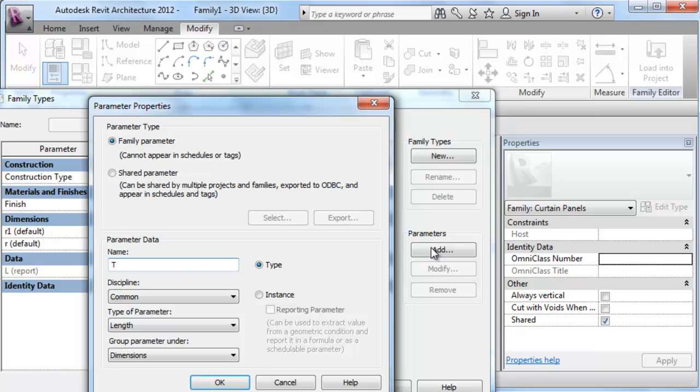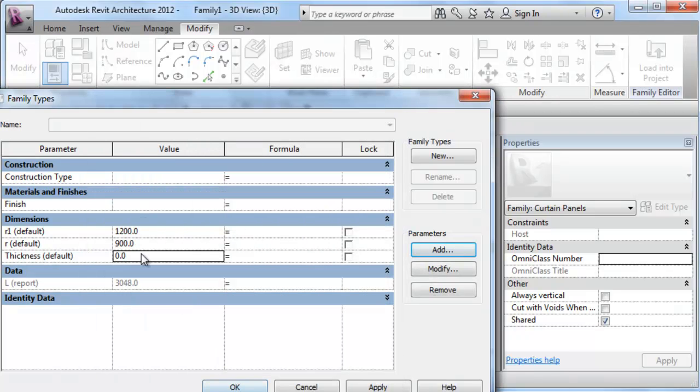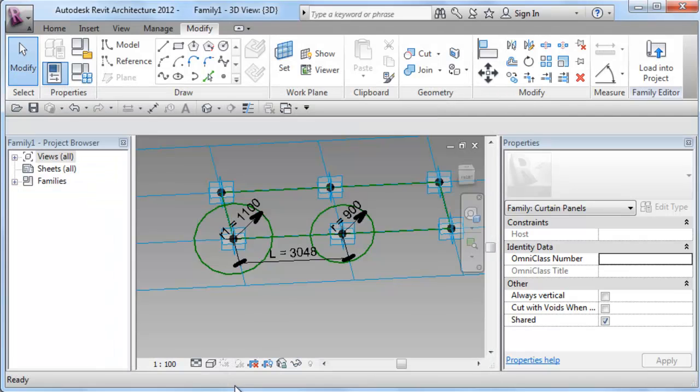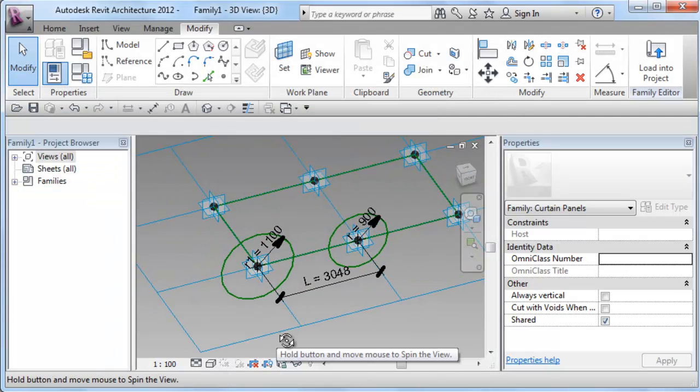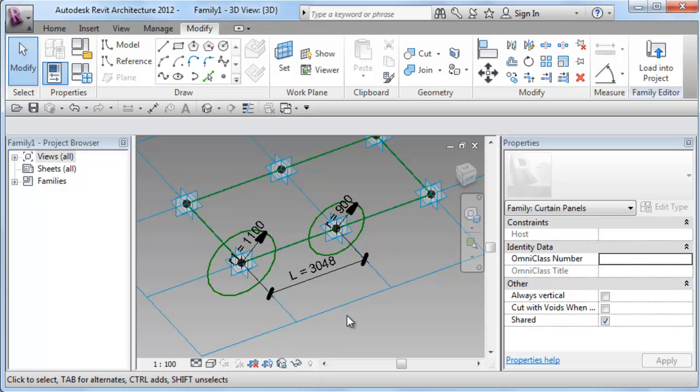called Thickness, because that would be the difference between these two circles. As we put a material in between, the thickness of that material would be the difference between the two radiuses. So I'll just assign that. It's not critical at the moment. I'll just call it 300 mil. And what I'm going to do with that thickness is say that the second circle is really the first circle plus the thickness itself. So if we just apply that, and now as you can see we have that circle.